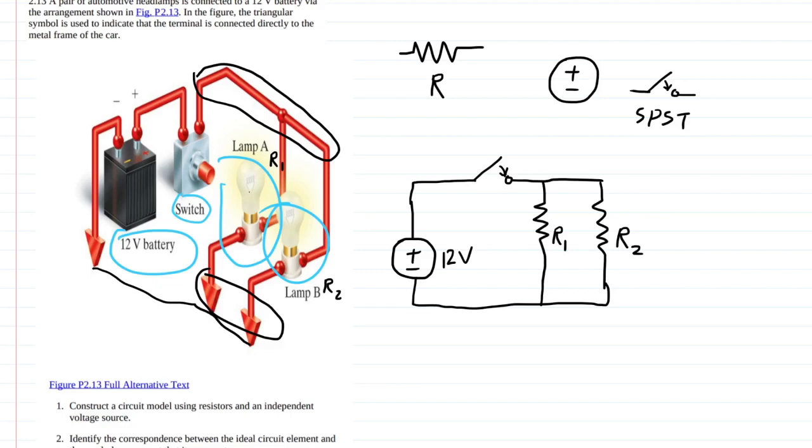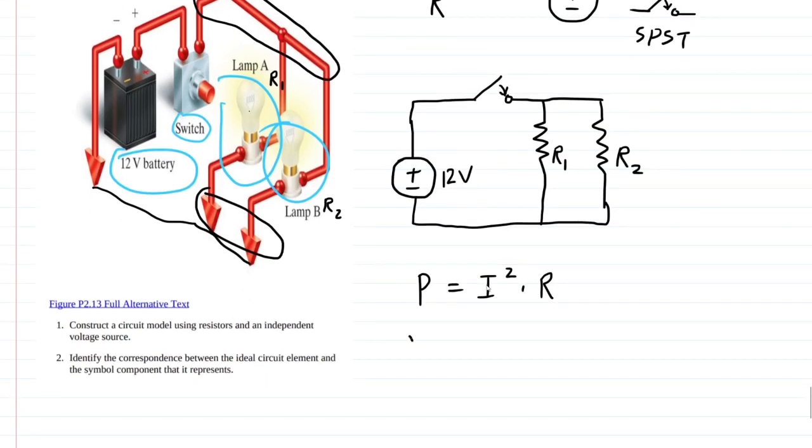And remember that power dissipated in resistors can be modeled as I squared times R. You can derive that quickly, because if you have V equals I times R, and P equals IV, you can write alternative representations. V squared over R will be power as well.